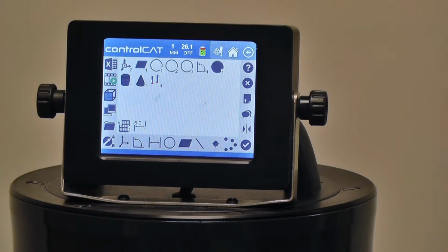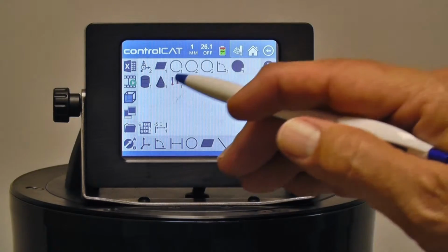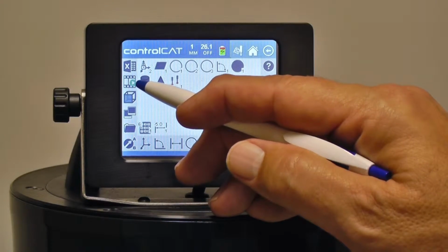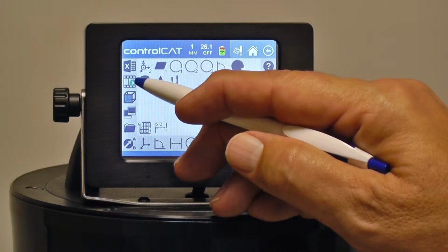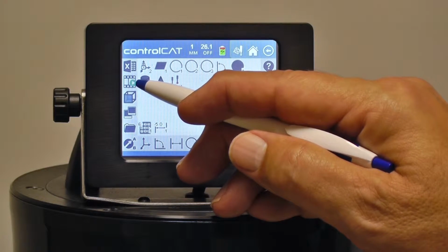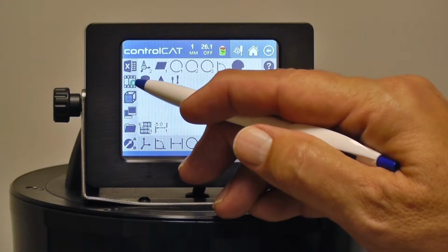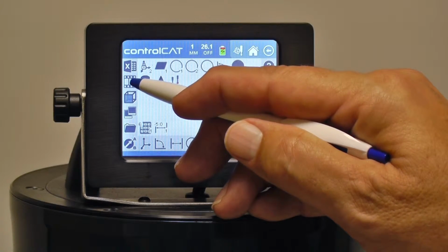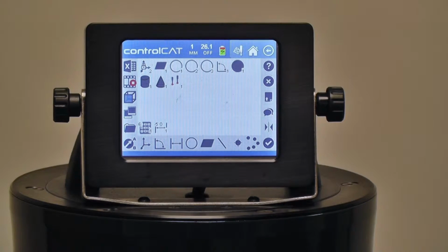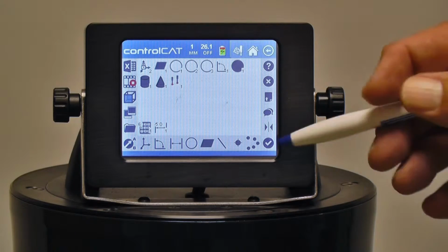So I still have my alignment locked in, but now I'm going to go to this icon which looks like a film strip, and in fact that is our program button or icon for macro program, same thing. So when I touch it, it gives us a red light and it tells us we're programming. So now it's going to remember every keystroke that I do moving forward.